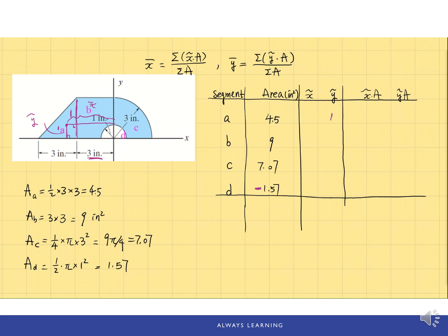But we're looking for the coordinate of this point. So this is the origin, and this centroid point is to the right. Therefore, it has a negative x coordinate. So we should put -4 for the x tilde.